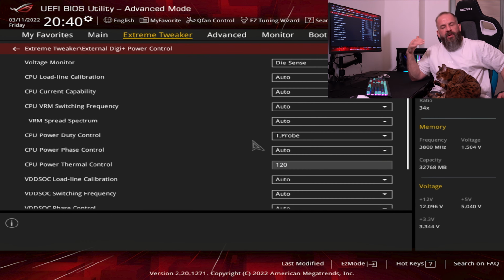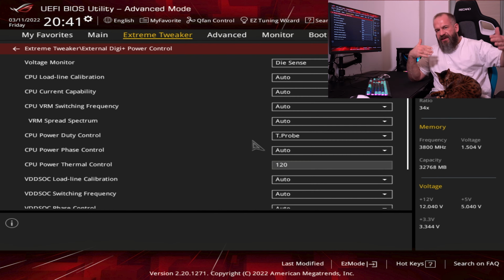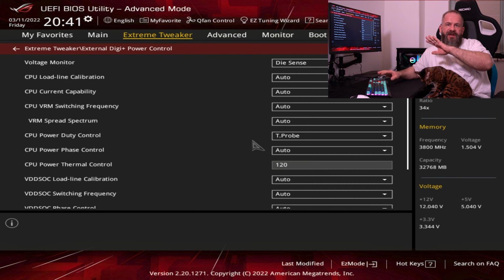Then this will be more extended now, and I also explain why. For those of you who have more knowledge about this kind of BIOS by ASUS and about PBO and curve optimizing, what we're doing here right now is that basically this one should be disabled by the pure way I'm overclocking right now, by those fixed clocks by CCX. But to be honest, those load line calibration settings are still somewhere in the background, and if you just put it on auto or too low, it feels like the stability of the system is not that good. If you set it to real values, which would fit the numbers you have set in the cores, so in the CCX 0 and 1 settings, I'm just setting it up right now and explaining it a little bit.